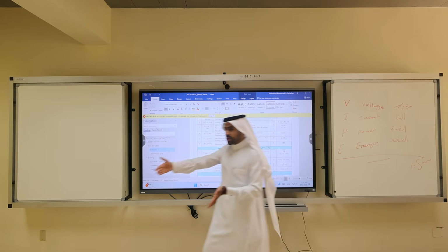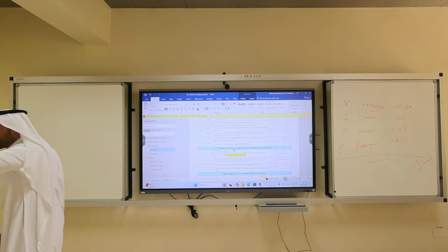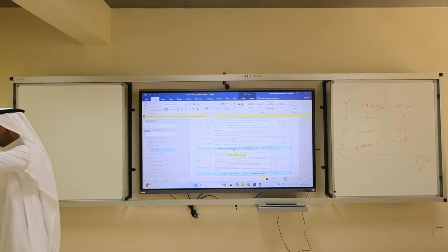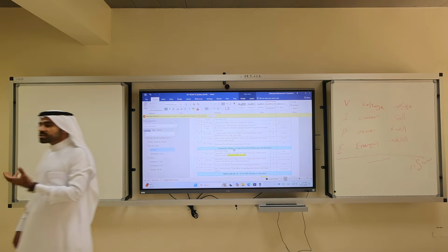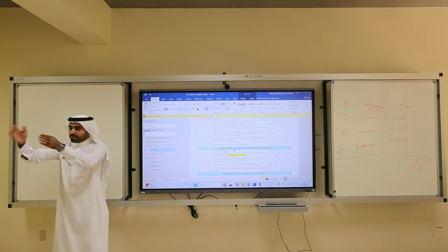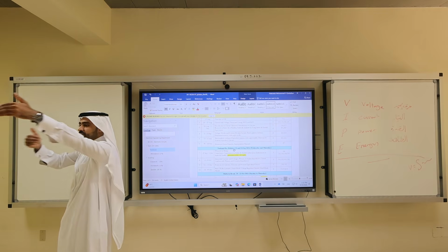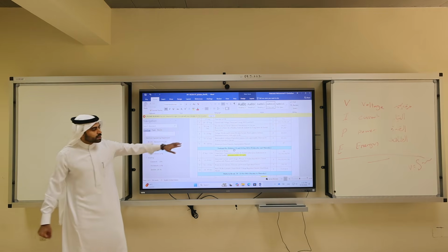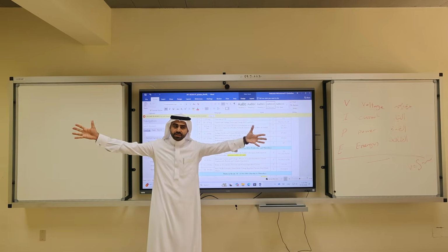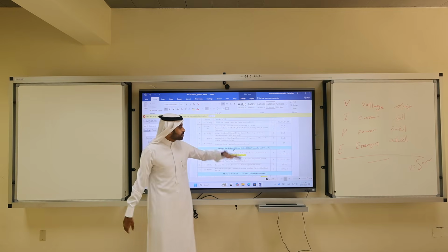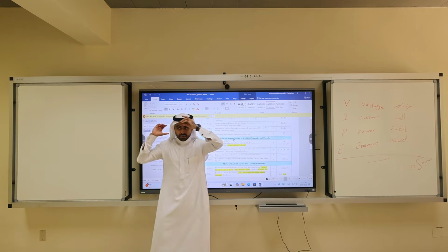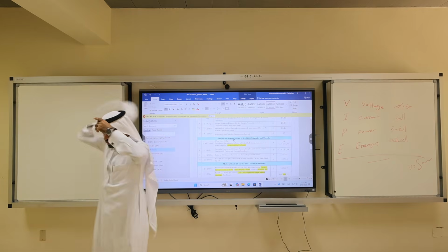Then we will go over the circuit elements and how to do the circuits. Are the elements in series? For example, are you guys in series or parallel? You are parallel. Yes. Are you in series, the three? Yes. So series requires having the same flow, while parallel means they have the same pressure. That's easier. We'll talk about some techniques: how can we simplify complicated circuits to simple circuits? Then we'll talk about the VDR and CDR, voltage divider rule and current divider rule.